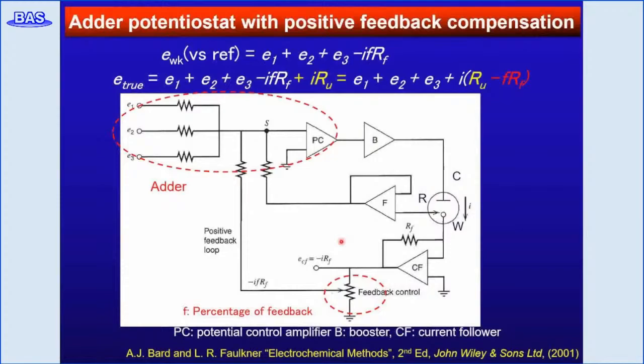This is one of the full potentiostat systems based on the potential control amplifier, in another configuration. I'm not that good at circuit engineering, so I could not explain the details of this circuit, but from the top, 3 terminals for separate current sources were added. By these 3 terminals, we can apply different complex waveforms, such as ramp or sinusoidal waves.